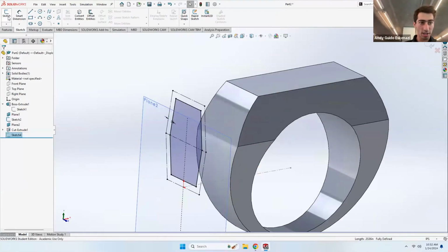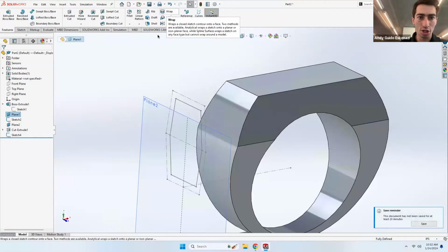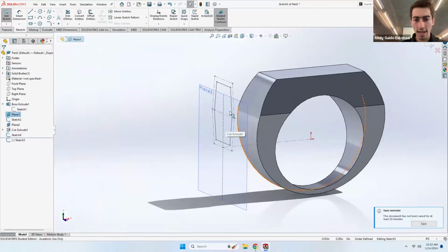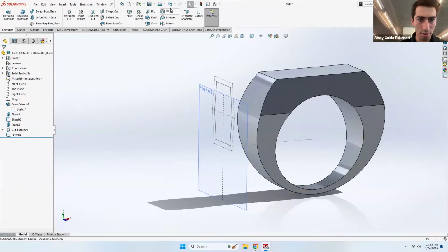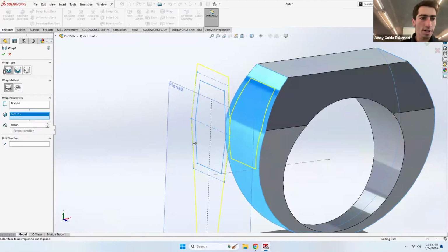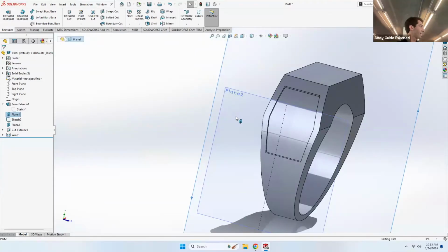But now I can exit my sketch and go to features and go to our friend wrap, which is this command right there. So I can click on wrap and then click on this plane. Actually, I didn't click properly. No. Let me go to wrap and then click in there. And then when it's asking for surface, click on that surface. So now what is exactly the wrap I want to do? I want to wrap it inwards and I'm going to invert it by 0.02. So look at the effect that it induces. Exactly that. So not bad, right? I think it looks pretty decent.